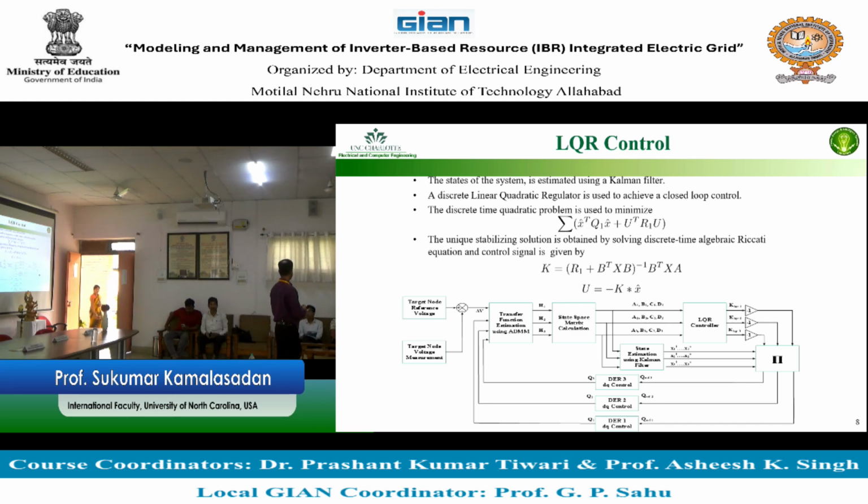Are we sending reactive power from the DER? No. We are changing the reactive power. Who changes the reactive power? Inverter changes the reactive power from the DER. So we are actually sending inverter set points to the smart inverter basically. How the inverter changes the power inside the inverter, that's the local control or the device level control. We are not talking about that. We are still on that level.